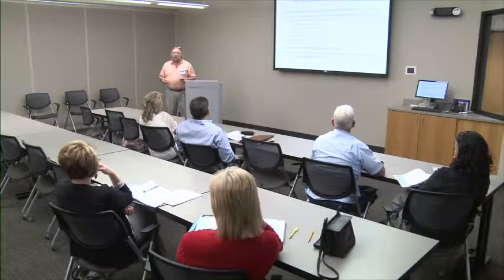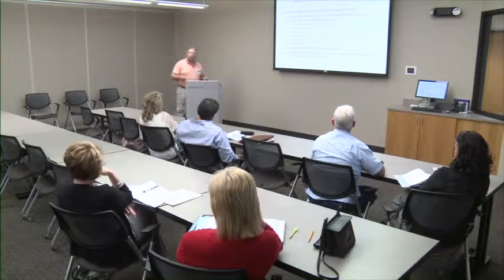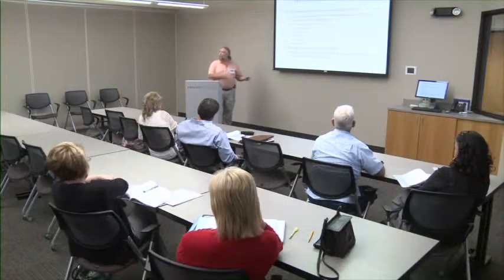All these people, if we have this plan, we can provide them with information that says, you know, we're going to need that steel on such and such a date because that's when we're supposed to put it in the ground. So it would be nice if it actually arrived here before that date. Okay, so I can look at it and say, well, I need air conditioning units for this building, and we're supposed to set the air conditioning units on the first weekend in March. But the air conditioning units actually take 3 weeks to be delivered, so then I need to order them at least 3 weeks before they need to be delivered.